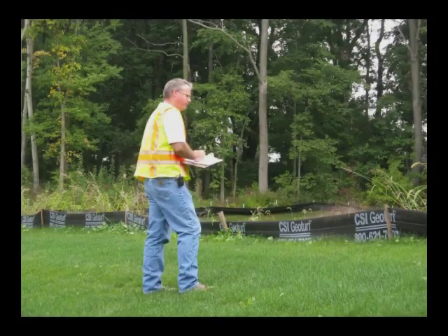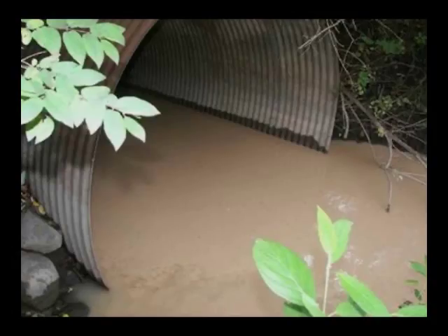It is necessary to ensure that the site is truly stable before terminating the coverage. A stable site has all permanent structures in place and the vegetation is fully developed. Remember, any stormwater that contains sediment and other pollutants discharging to surface waters of the state may be a violation of Part 31, Part 91, and Permit by Rule.